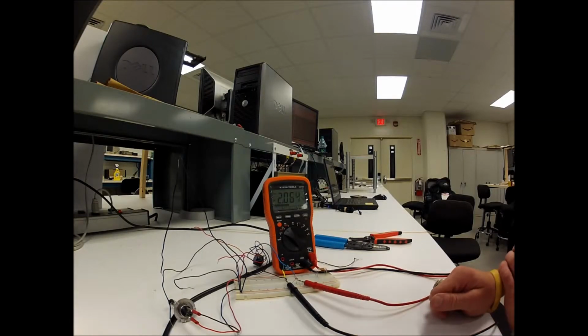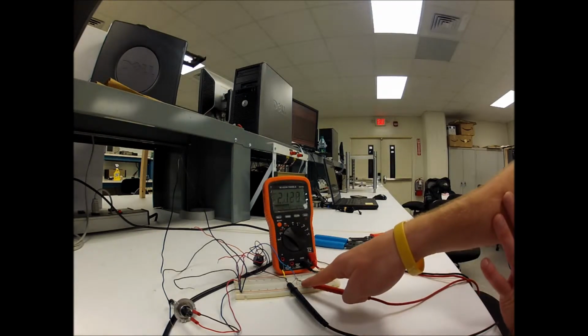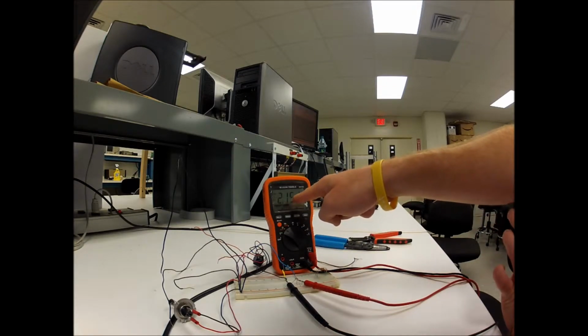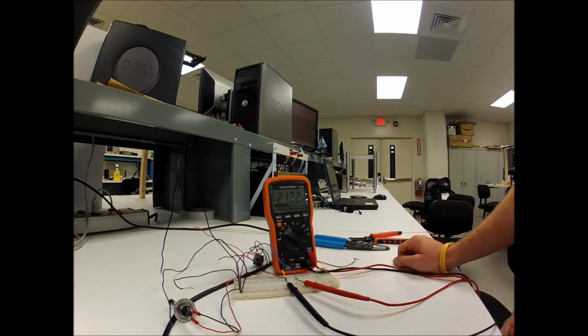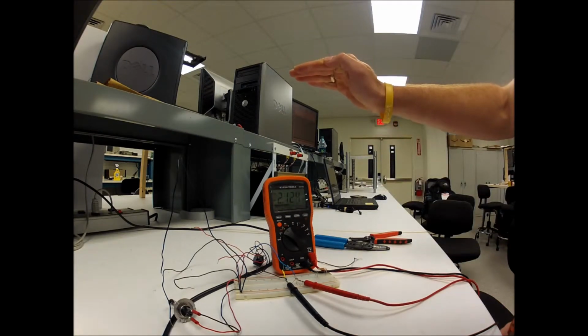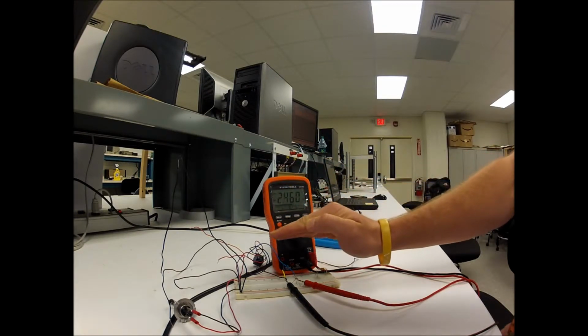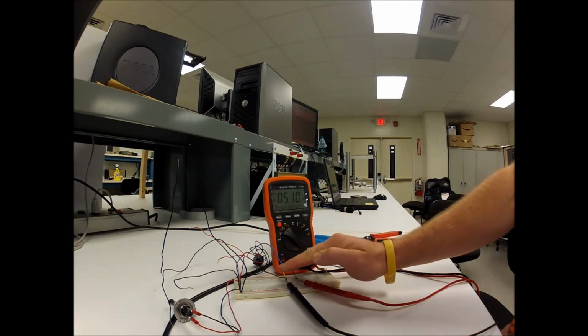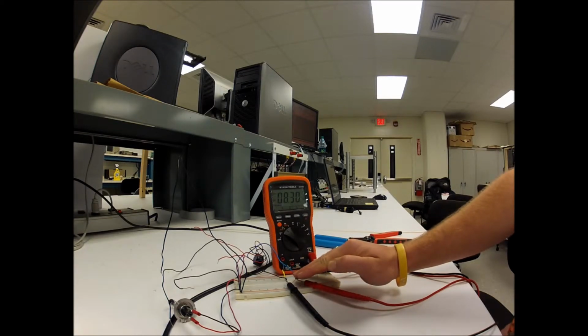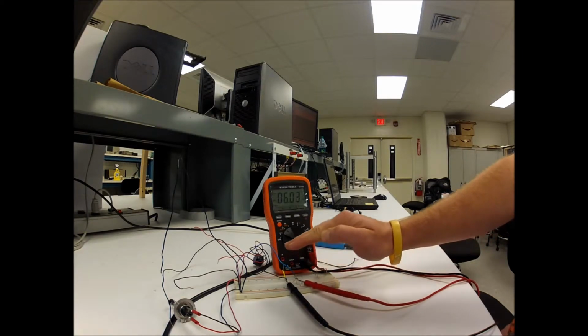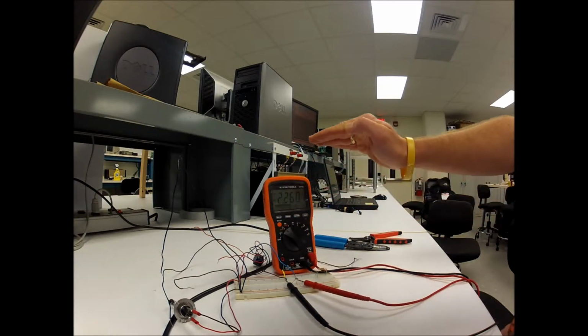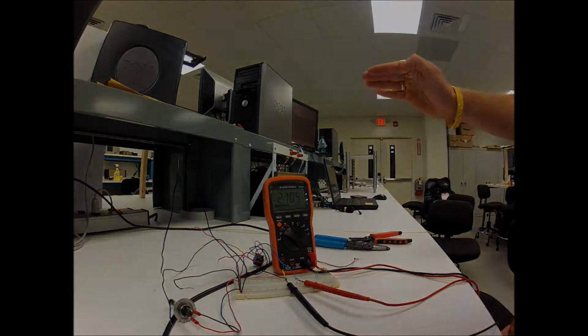I just wanted to demonstrate a little bit how a photocell works and how it changes resistance as more or less light hits it. That's the photocell right there, and I've got the resistance in K ohms displaying on the screen there. If you watch, it starts at about 2K, and as I bring my hand closer and get less and less light on the photocell, the resistance increases. As I move my hand away, the resistance decreases. And that's the basic operation of a photocell.